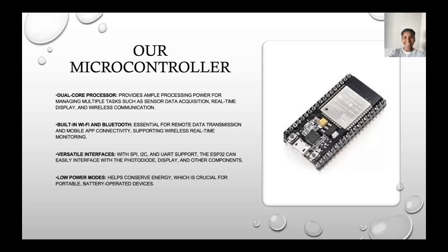It also is versatile with different interfaces. It has built-in SPI, I2C, and UART support, which is very important for the amount of data we'd be configuring. It also has low power modes, so it will help conserve its own energy. And that's really important because our device obviously has different power being received in different aspects, so we want to make sure that it would have that self-efficiency.